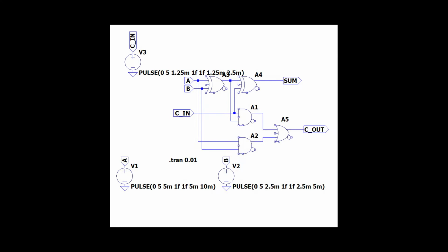So to design a 4-bit full multiplier circuit for unsigned integer multiplication, we need to design a 4-bit full adder as shown in the figure. The 1-bit adder circuit consists of 2 XOR gates, 2 AND gates, and 1 OR gate. In the adder circuit, carry in bit Cin, bit A and bit B are the 3 inputs, while the sum S and carry out are the outputs.